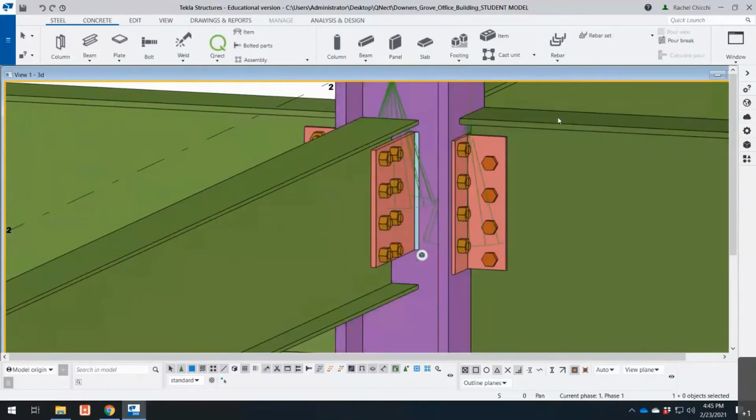off. Beam to column web connections have a number of difficulties due to lack of space to work with between the column flanges. If you have a conventional shear tab, meaning that it only extends the bolts out a few inches from the face of the column web, you likely would have a hard time trying to get an impact wrench in there between the column flanges in order to tighten the bolts. Thus, bolting directly to the web by some means, or extending out the connection so that you can bolt transversely from the beam in an area where it's not conflicting with the column, such as what's shown here, these are really preferable methods of connecting.